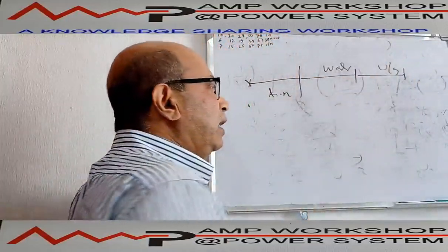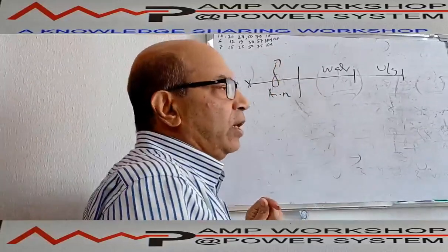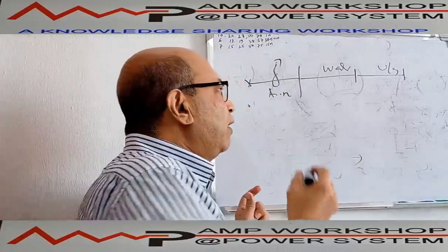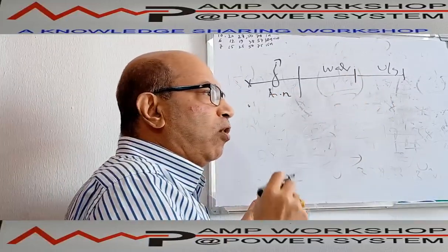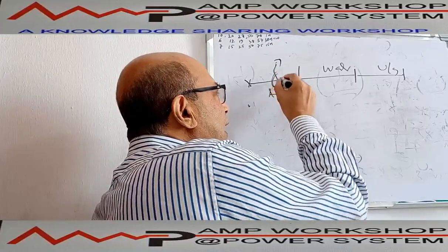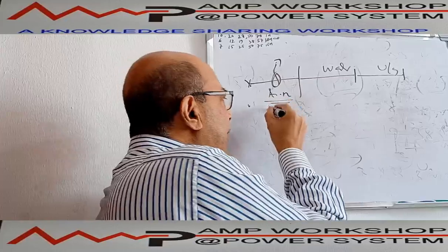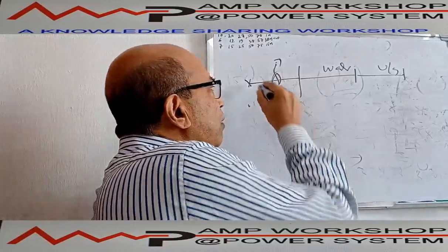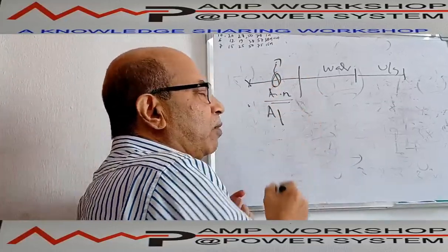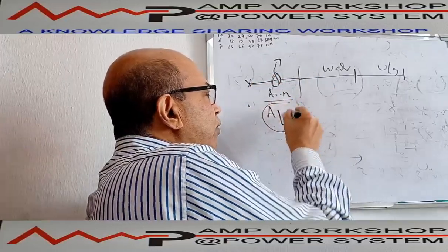If the cable is laid in this way, then for each area we have to calculate the cross-section area. Here voltage drop is not the very important part, but we have to calculate what current carrying capacity is required. Suppose the current carrying capacity required is A1 for the cable laid here, considering the full load current and the voltage drop, we need A1 cross section area.